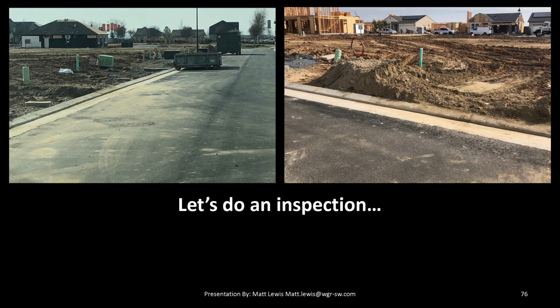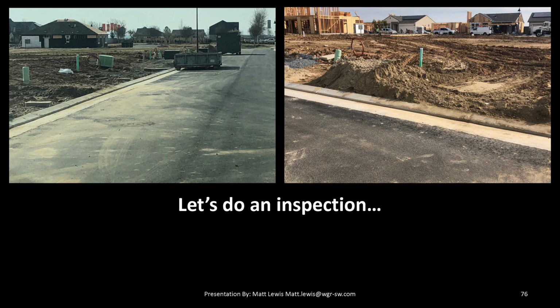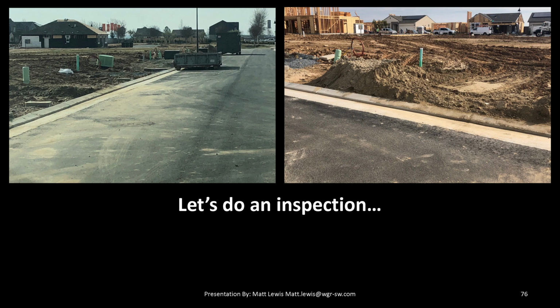Okay, so this one, no help from me on this part. Track out, is that what I heard? Sweeping? No perimeter controls. Yep. Stockpile right next to the curb. Exposed soil that's definitely been exposed for longer than 14 days. The stockpile, they might be able to get around saying it's active. But yeah, they've just got a ton. And also you can see the further trash bins there in the background are not covered.